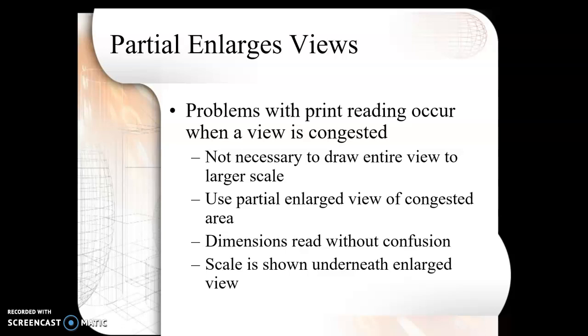But if it's just a small portion of the drawing, you may not want to increase the scale of the entire drawing. That may unnecessarily make the drawing bigger than it needs to be. So you might just want to take part of that drawing and blow it up to a bigger scale so that it can be seen in more detail. And that would be what we call a partial enlarged view.